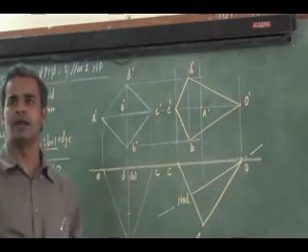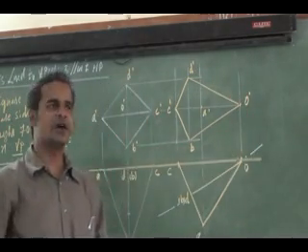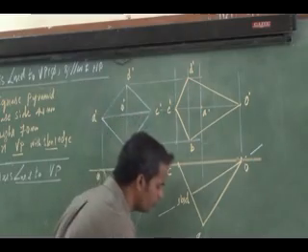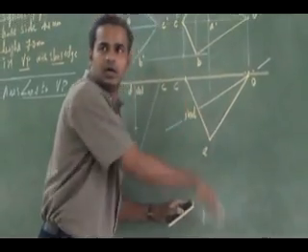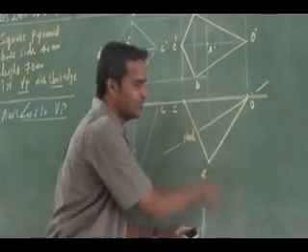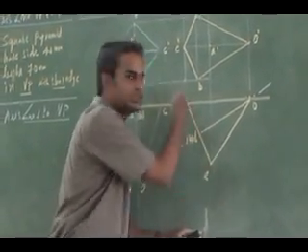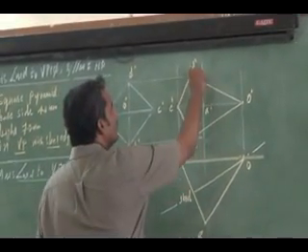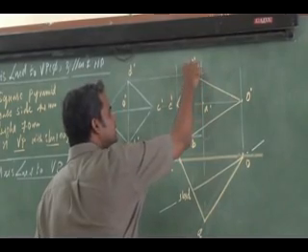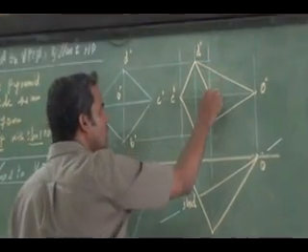It will be a visible one. Then as for the base, look at the top view from the bottom. I can see the whole base, so the base is fully visible for me. Base edges I can show as fully visible lines.